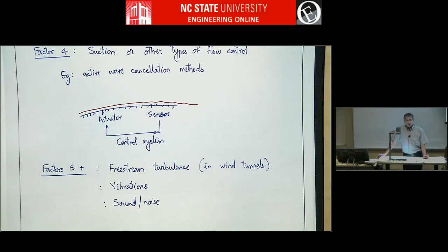So if you put a low Reynolds number airfoil in a highly turbulent wind tunnel, the laminar separation bubble may get tripped because of the free stream turbulence. And so that airfoil may actually have less drag than if you put it in a very clean tunnel, clean in quotes, meaning the flow is extremely low turbulence. Then the laminar separation bubble will be pretty big because the flow will be laminar, it wants to stay laminar. So that's one reason why turbulence intensity is something that's quantified in most tunnels.